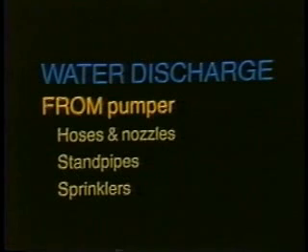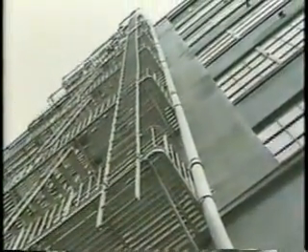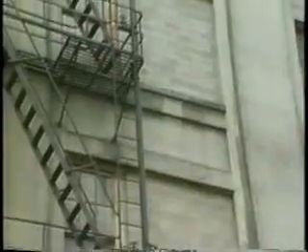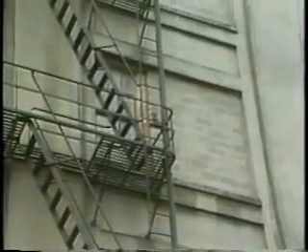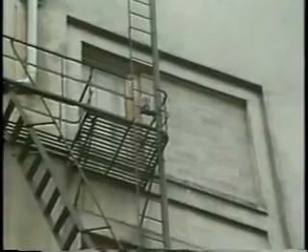In addition to supplying water to hoses and nozzles, pumpers can also support standpipes and building sprinkler systems. Standpipes are found in many buildings and are designed to be utilized by fire departments to transport water, especially to higher elevations, reducing the need for advancing fire hose. Standpipes can be dry, not filled with water, or charged with water from the building water service. Standpipes in colder climates mounted exterior to the building will usually be of the dry type because of the possibility of freezing.